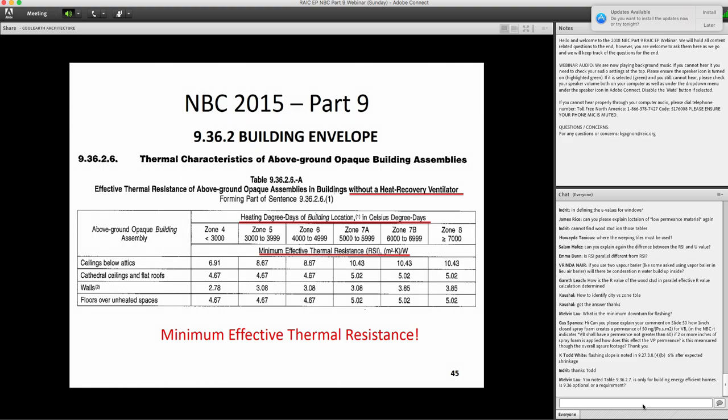In some cases, you connect that weeping tile to the below grade slab gravel, and that gravel is connected to the sump pump. So in case of flash flooding or a water table rise, you will be able to extract that excessive amount of water through the weeping tile.